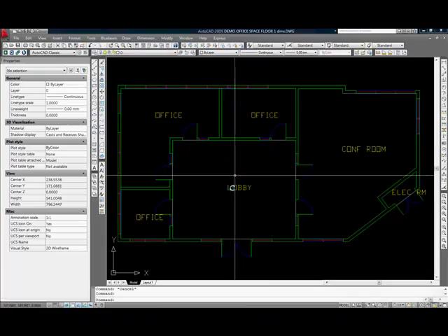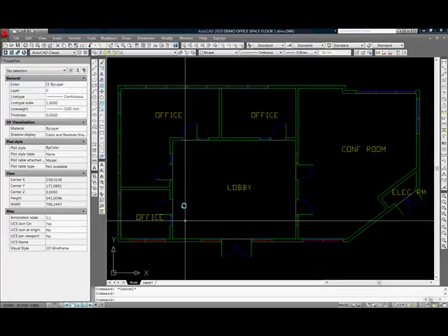So let's say I'm in the lobby area here, and we're going to just lay out this lobby. It's 20 feet by 25 feet. So I would hit an arrow key, and I would disto the measurement, and we're just going to manually enter 20 feet. And it draws the first line on the full height wall layer. If I click on that, it highlights it and it shows me its attributes. It's 20 feet, the direction is 90 degrees, and it's the full height layer.